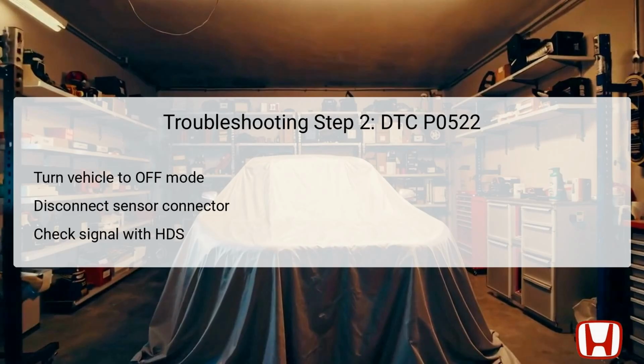The objective is to see if the measurement is again below the threshold of 0.18 volts. If it's below this threshold, it helps confirm the suspected failure area and allows you to move on to the next steps. However, if the readings do not fall under this threshold, further investigation is needed, particularly on the wiring and connections from the rocker arm oil pressure sensor to the PCM.